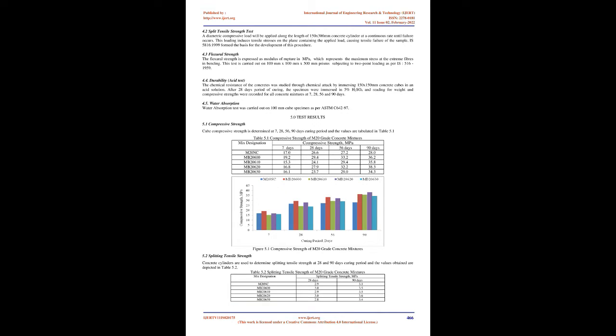Bacteria precipitate calcium carbonate, calcite, CaCO3. The physical and mechanical properties of calcite are closely similar to those of hardened concrete, and hence it can be used as a crack-filling agent for concrete structures. It is produced biologically and does not possess any harmful chemicals. Also, its production is self-sustained, happens without any human support, and has the potential to remediate every minute crack. These properties of calcite make it a perfect filling material of cracks developed in concrete.